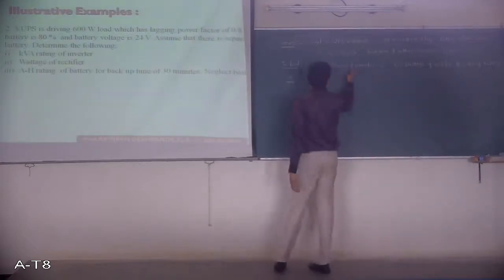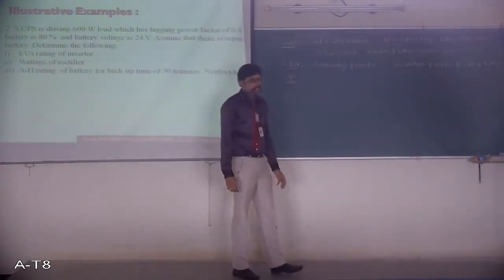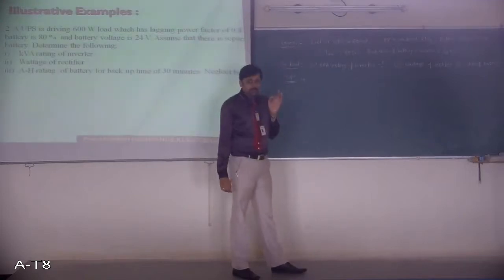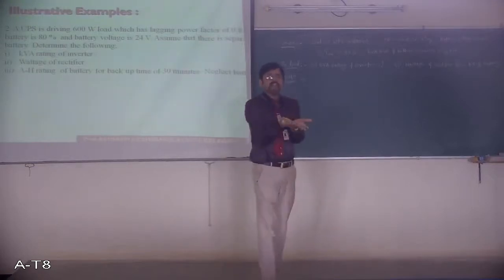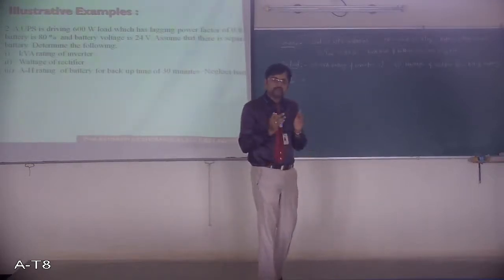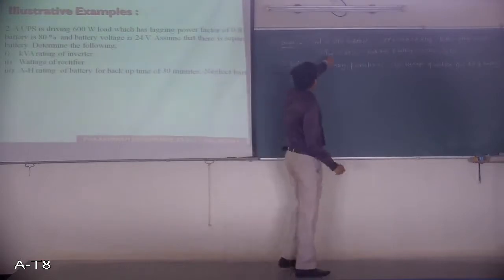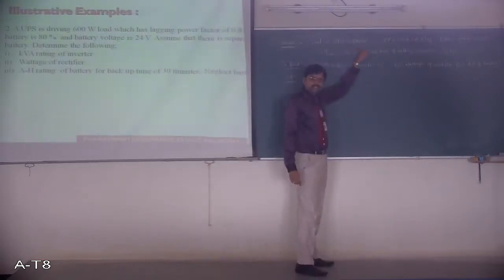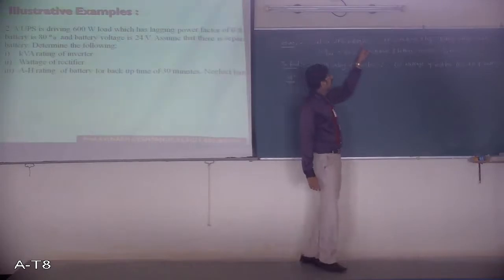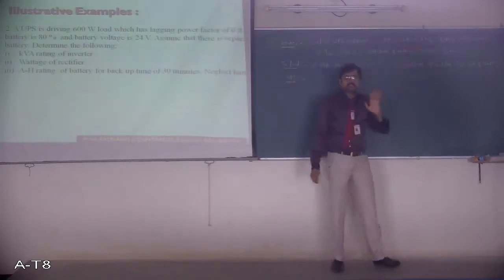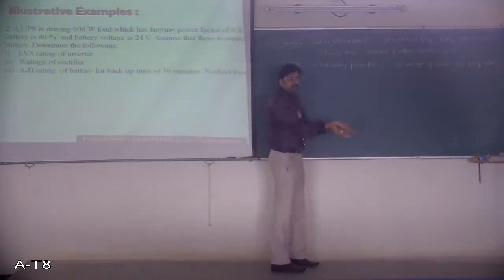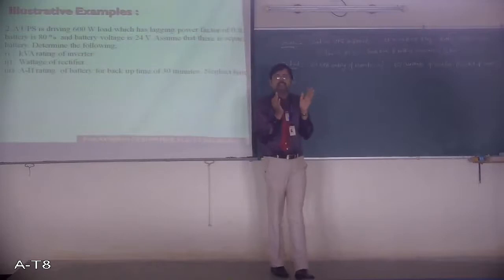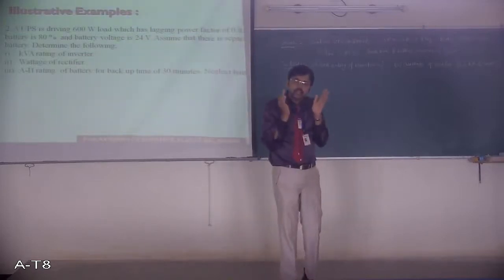First one is the KVA rating of the inverter. But here remember the load power is given to us. See, the inverter is feeding the load itself, so the output of the inverter is known. Only thing is it is mentioned in terms of active power, which is in terms of watts, and the load power factor is also known. So the output of the inverter itself is the load power, so at least that should be the size of the inverter. I hope you are understanding what I am talking about.